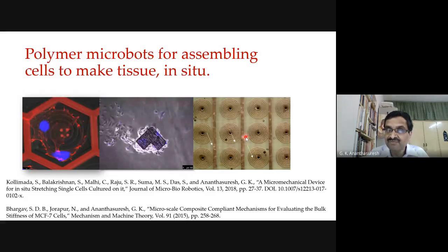Again, electromagnet force is also quite high compared to electrostatic force. Now people are moving towards magnetic actuation of micro robots. We have this array of coils and a chip, and these are the little robots that you see, different shaped robots. And one of them I'm showing here, another one showing here, where biological cells can be grown on them, so we can shepherd the cells where we want and do lots of things. These are the ones that go inside the body and set up a hospital inside the body.